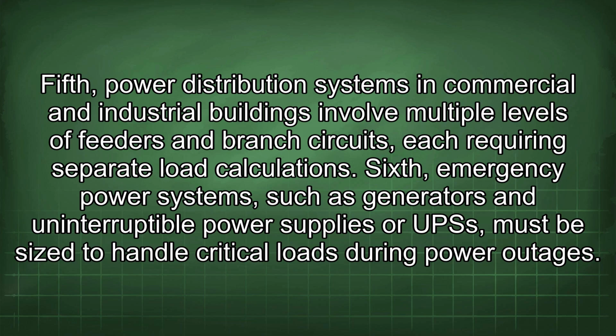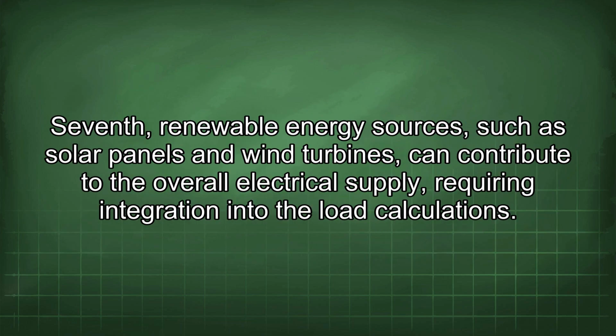Sixth, emergency power systems, such as generators and uninterruptible power supplies, or UPS, must be sized to handle critical loads during power outages. Seventh, renewable energy sources, such as solar panels and wind turbines, can contribute to the overall electrical supply, requiring integration into the load calculations.